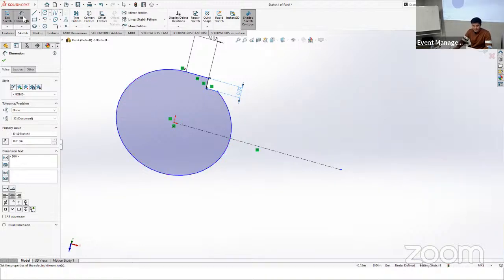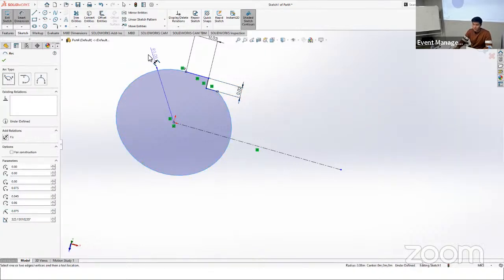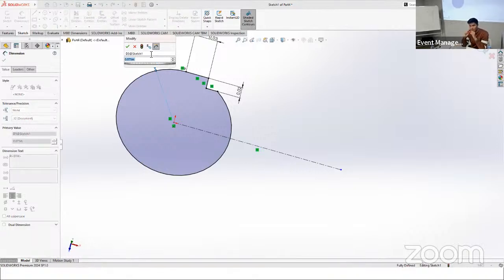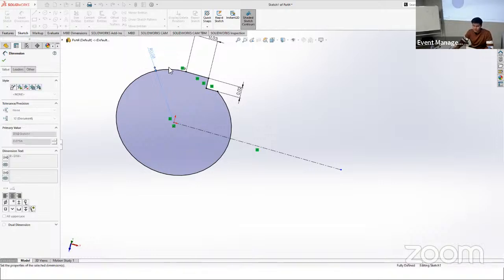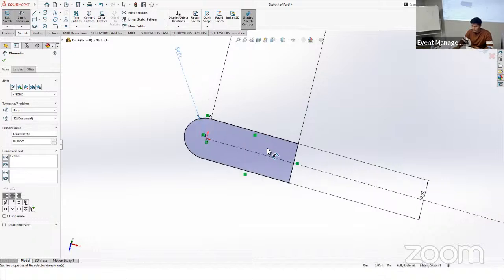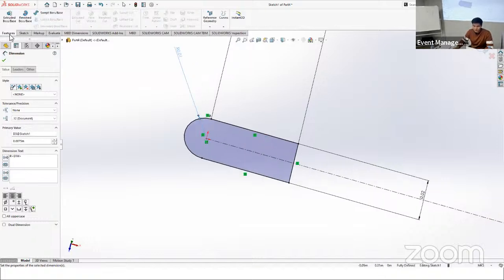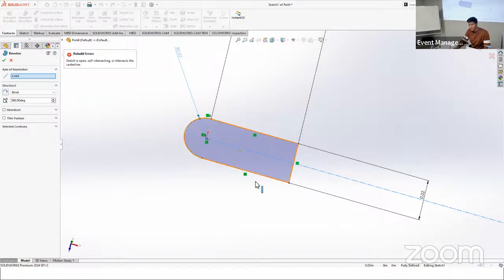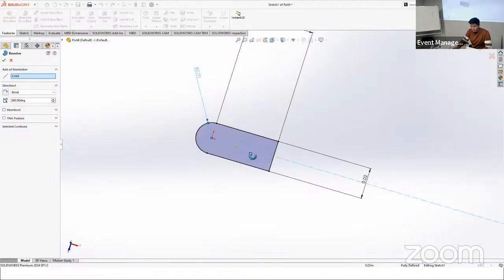And after that, we also should enter the radius of the top part. So if our diameter here is 1.5, our radius should be half of that. So it's going to be 0.015 divided by 2. So we actually can enter some simple formulas. It detects it automatically. And that's what we have. And we apply a revolved boss. And this time it should be working, I guess. Sketch is open. I don't get why it's saying that it's open.